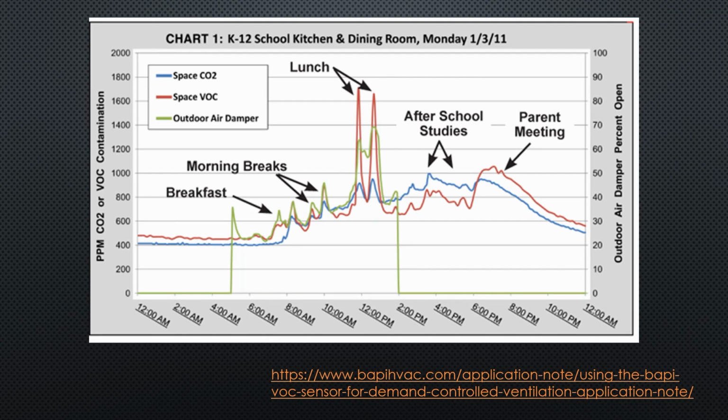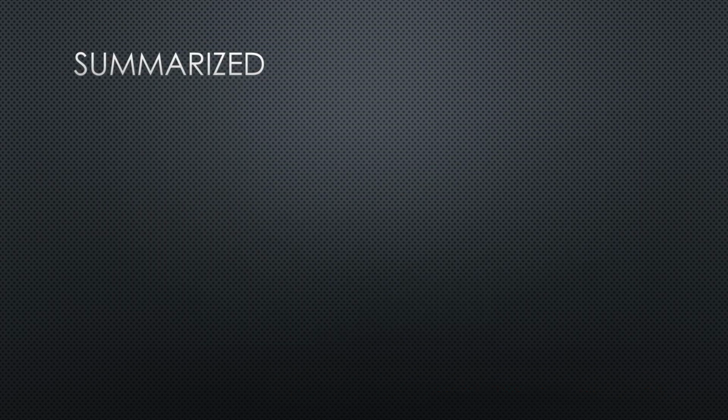This effect is also visible in the diagram where we see the measurements of a proper CO2 and a VOC sensor placed in a room of a school building. During pizza cooking, the VOC measurements were very high. I'm pretty sure pizza odor does not trigger complaints about drowsiness or sleepiness, at least not with young people.